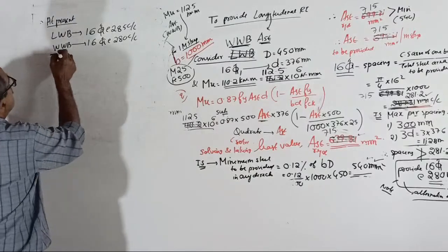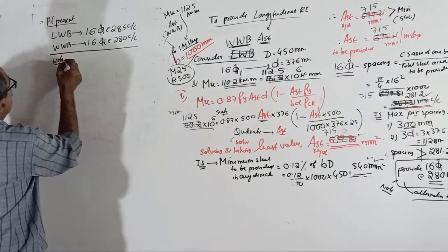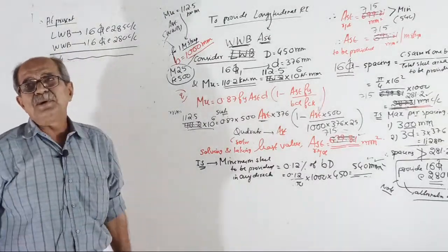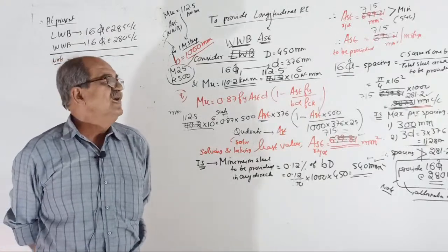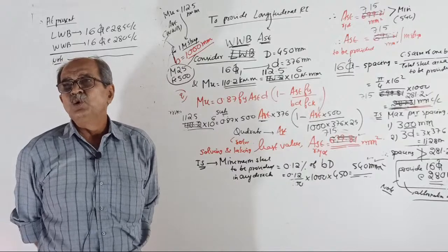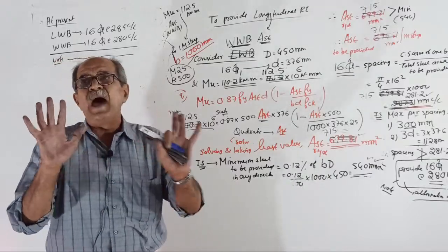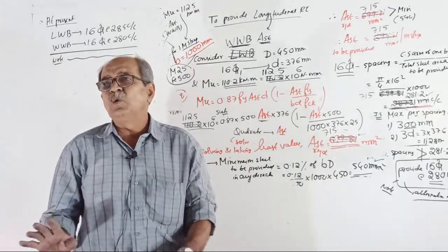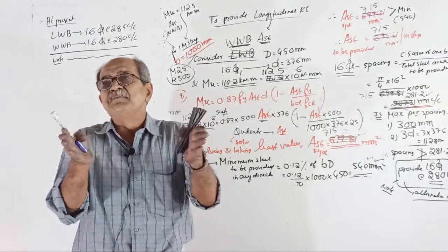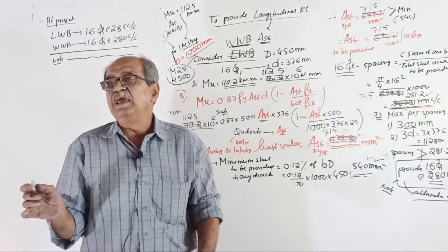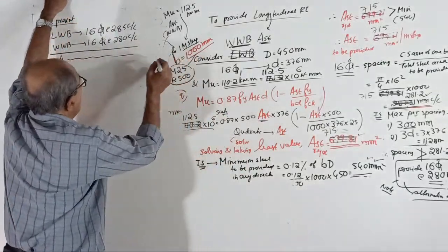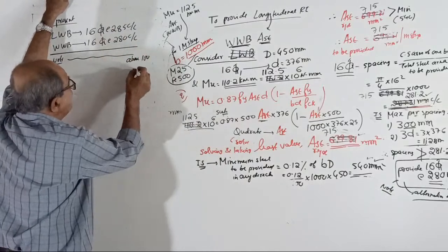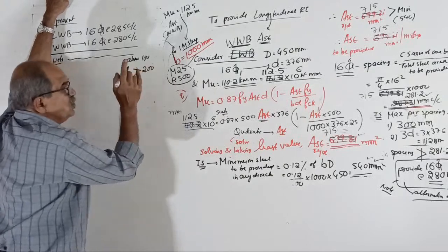Now make a note. You write, I am not writing here. Spacing of 285, etc., is practically not accepted. They will say it is too high. Usually for a compact action, bars should be closer. Therefore, usually they do not want bars closer than 100 mm. Practically, people want spacing above 100, that is 4 inches, and not more than 200.